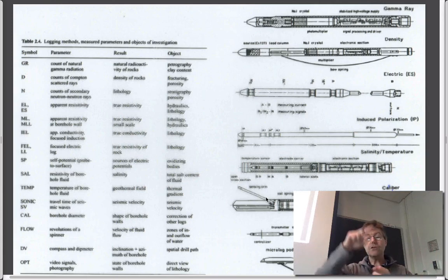It might measure the electrical resistivity along the borehole in exactly the same way as a Schlumberger probe measures it on the ground. You put energy into the wall at one place, and you have a voltmeter that measures the difference in volts at another location. It might have a little impeller that measures the flow velocity in the borehole as you drop the probe down, and then as you pull it back up. If you subtract the two measurements of the velocity of that impeller, you can see whether water is flowing into the borehole at some place and then flowing out at some place, because there'll be a signal in there. It's exactly the example we use to talk about substantial derivatives, moving frames of reference in 303.